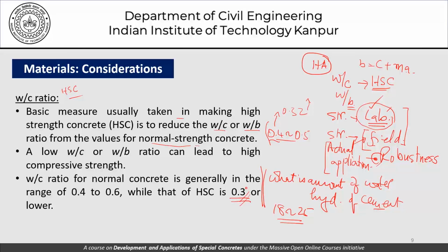All the water that is supposed to be there will be consumed in the hydration of the cement that we are using. Meaning thereby that this water which has been added there cannot be allowed to escape. In fact, if it does not escape and is consumed in the hydration, the porosity of the concrete will go down. And this is at the root of our thought process, that if porosity goes down, obviously the strength will increase.